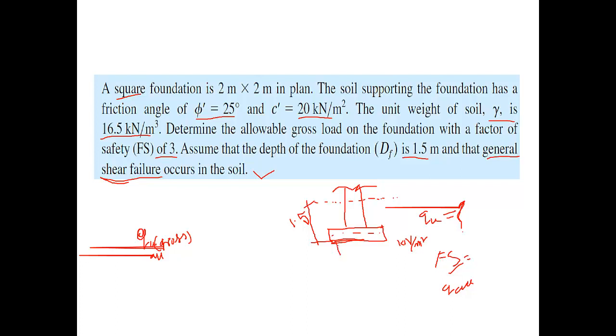But they said you need to find out the load. How much load can be taken by this soil, right? So what will be the total load? You know the area is 2 into 2. If you simply multiply the QAL with this, you get the load, stress into area. So you get the load that we are considering. You clear now?